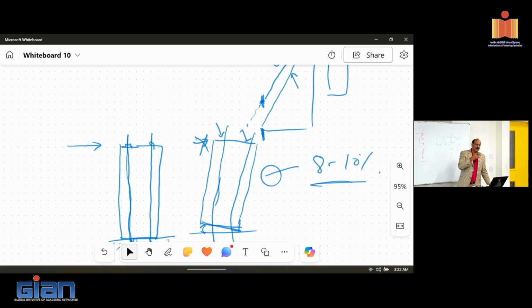I've done a number of tests in the last 10 to 15 years. I never lost a complete strand. In each of the tests we probably put through maybe 20 earthquakes. Never lost a strand. We have had fractured wires within a strand, one or two wires popped. That's to do with the quality of the wedge anchorage.